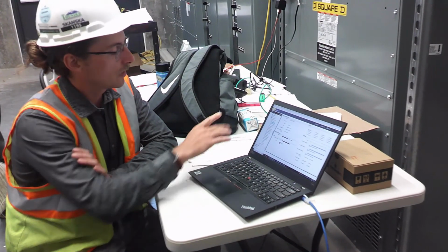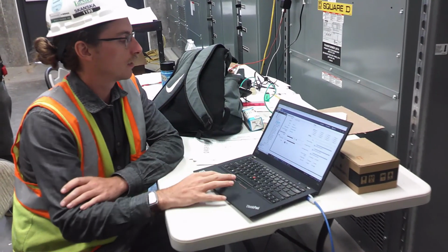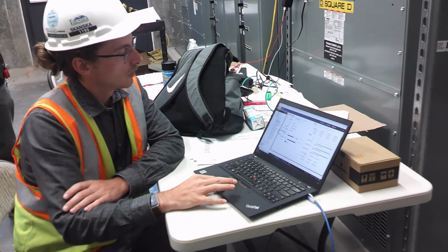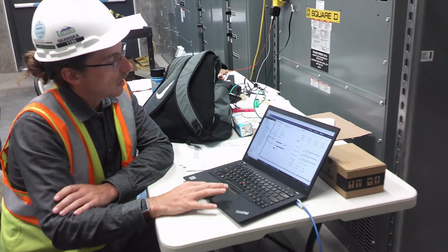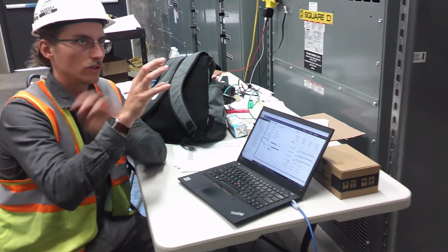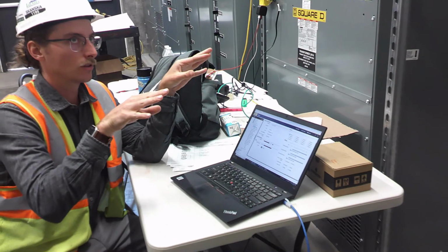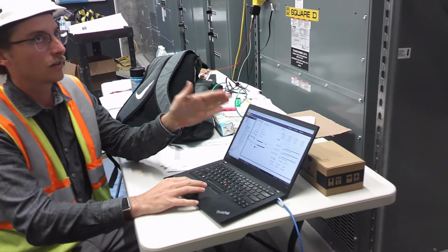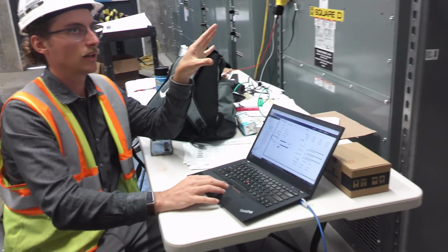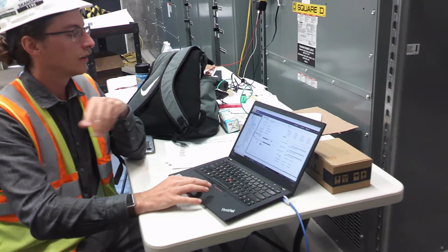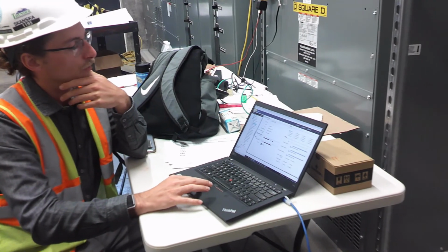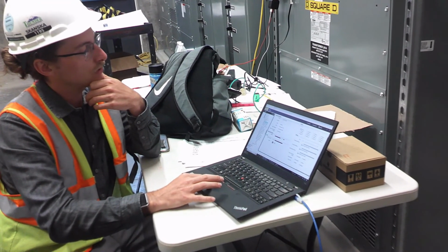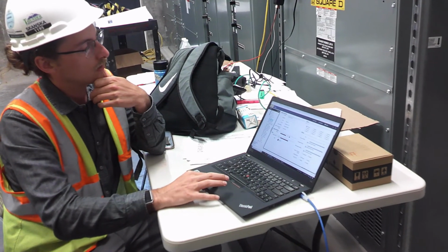So you'll see the way they're labeled. We have A and B and the different daylight zones. So you see A comma B because that controller is doing A and B, daylight zone 1. And since it's A first and B second, that means the first relay is going to be A and the second relay is going to be B. So you'll see AB dim 1, that means you're looking at A. If you see AB dim 2, that means you're looking at B.